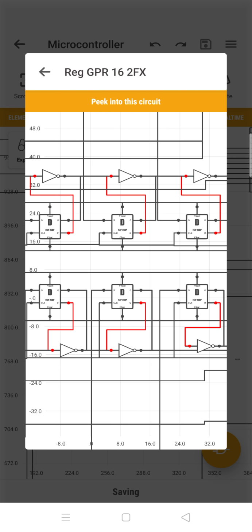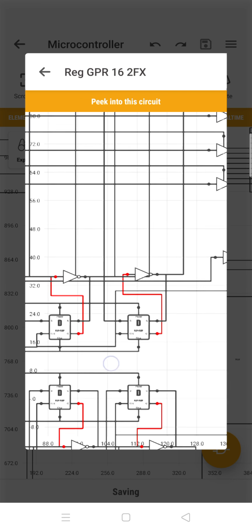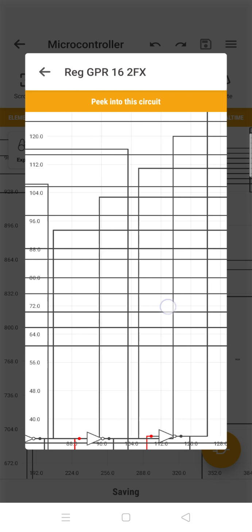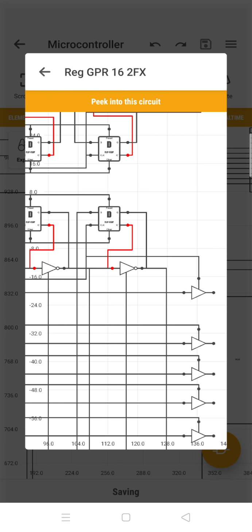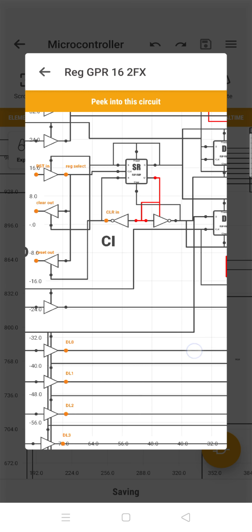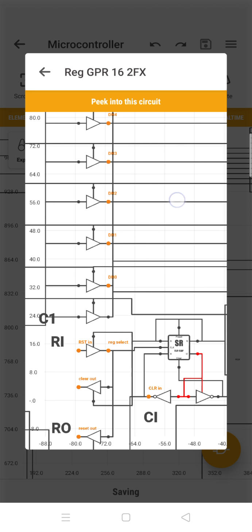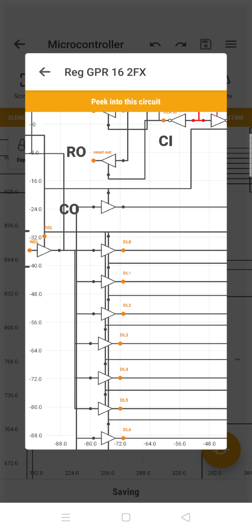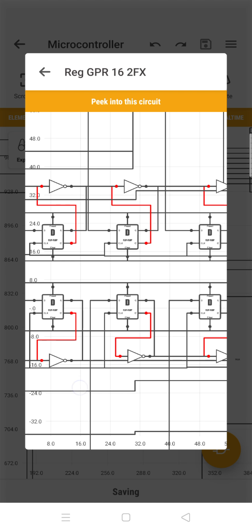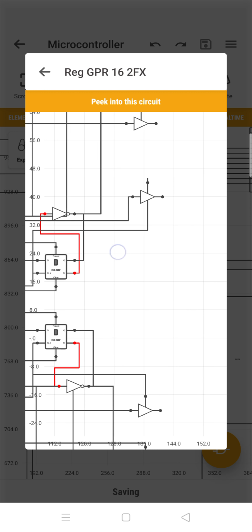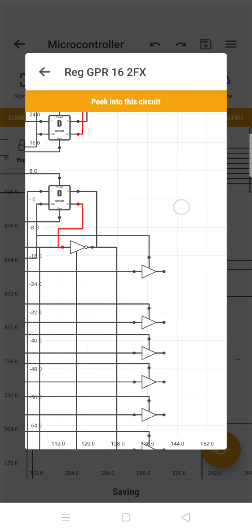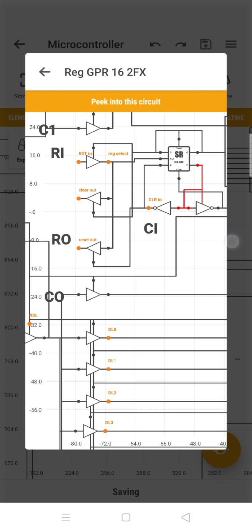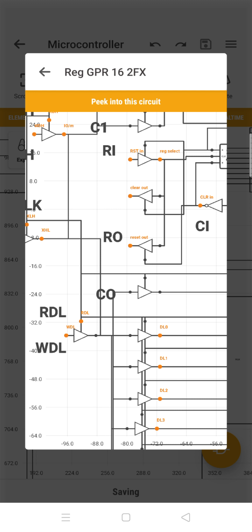So I put it as a kind of chip inside, so it is easier for you to look at how it works. The bus comes in, it's a data bus. About 8 data bus pins are there. This is the data in of the first 8 bits, and this is data in for the second 8 data bits. This is the 8 data bits going out, and this is another 8-bit data out. Control: how many controls are there for this thing? Just for a register, how many controls are there?